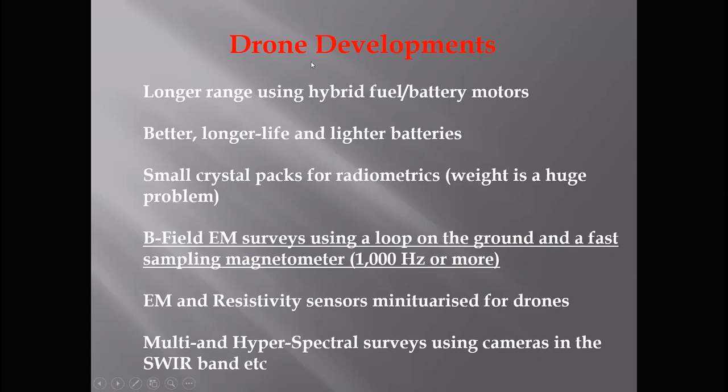So if I look at the drone developments that we're getting into now, of course, we're going to see a massive explosion in developments because everybody's starting to use these for various things. What we need is longer range. At the moment, we're using lithium polymer batteries, and you've got to have about 30 of them in the field, and you have to recharge them every 30 minutes. You have to have a full-on bakkie there with fans and fridges and recharging facilities and shade and everything. And these batteries are like 2,500 Rand each.